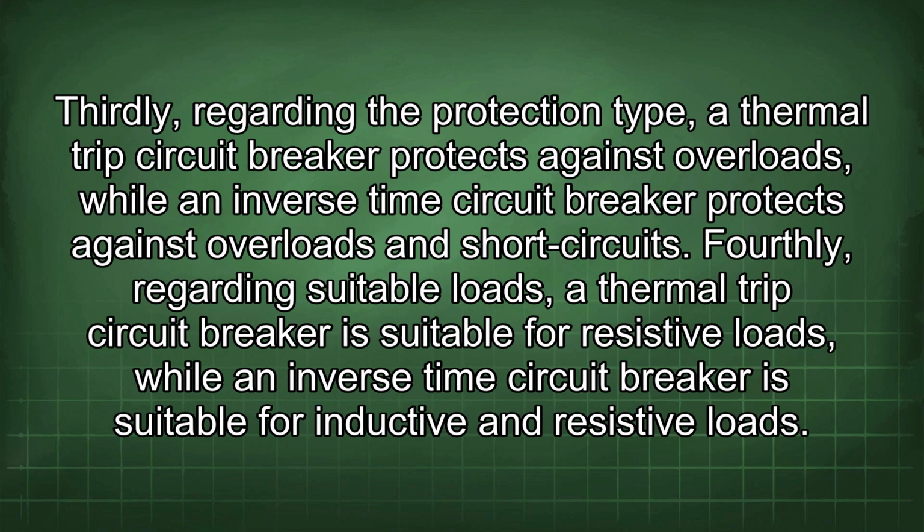Thirdly, regarding the protection type, a thermal trip circuit breaker protects against overloads, while an inverse time circuit breaker protects against overloads and short circuits. Fourthly, regarding suitable loads, a thermal trip circuit breaker is suitable for resistive loads, while an inverse time circuit breaker is suitable for inductive and resistive loads.